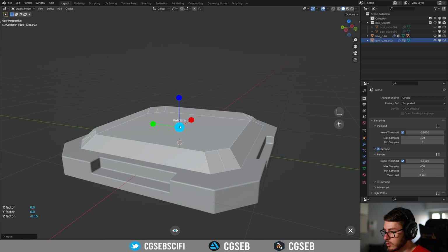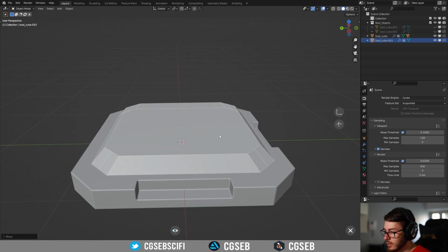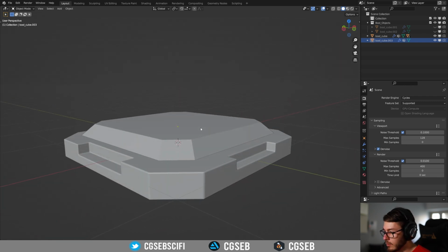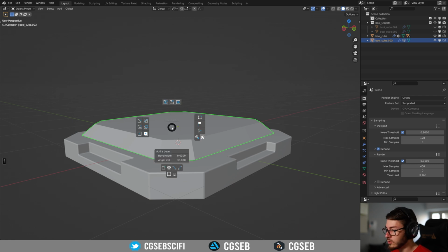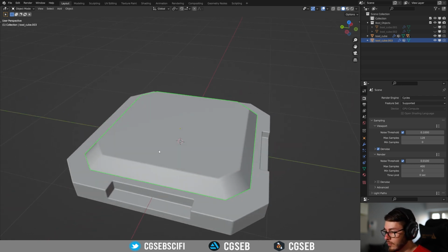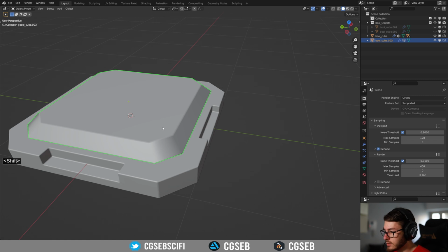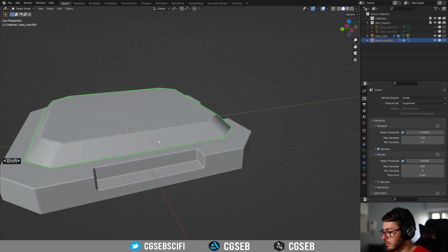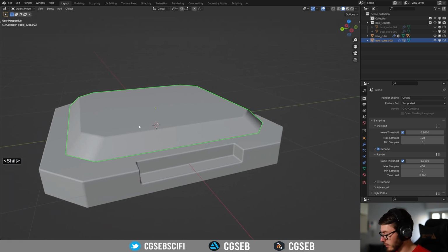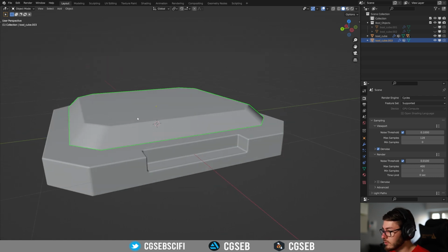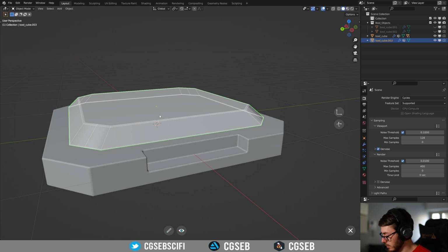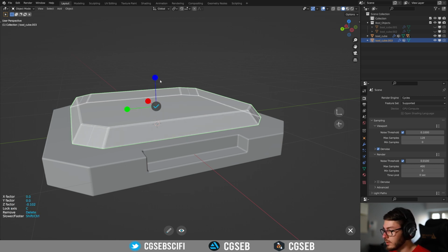So we can validate this, and we're going to right click. So here also we add a bevel, and then we see that here the bevel is actually clipping, and this is not working very well. So we're going to just go to the Fluent edit and again go to the taper and then move it until we have the bevel here.